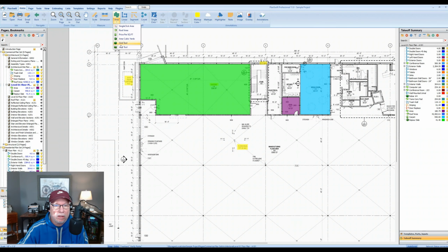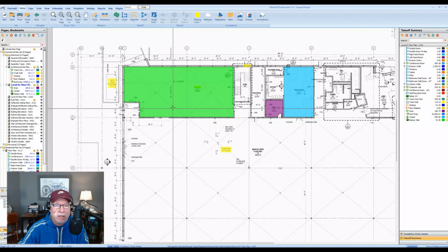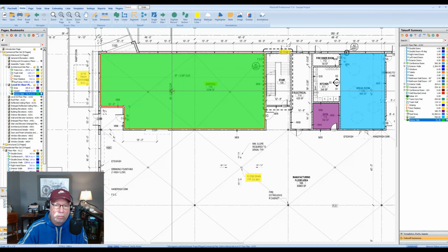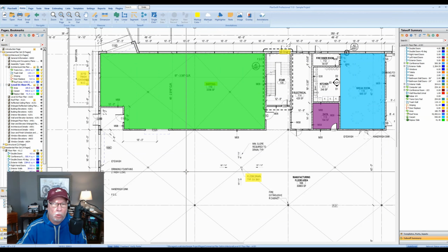So now we've done area cubic yards. And also, if we were building a template, once we did the square footage of the concrete, we could have it calculate automatically the amount of square feet or rolls or sheets of welded wire mesh. If we were having to put rebar on the slab, well, that's a different story. We need to know, well, what is the pattern of rebar? And that's where the grid tool really comes in.